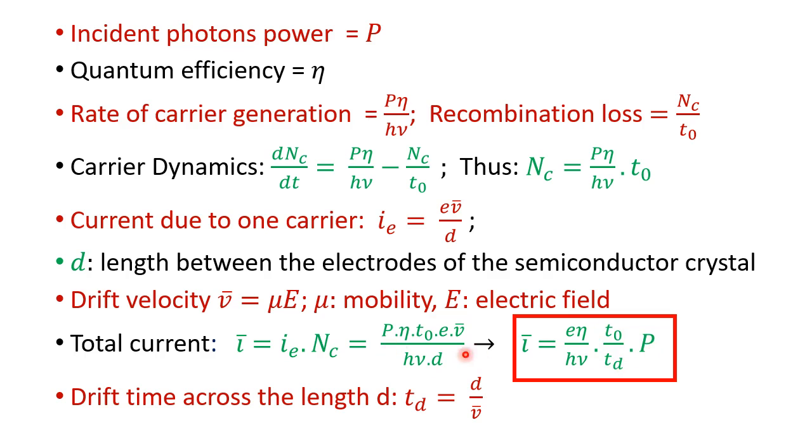This supports my statement which I had made earlier, that it's only this fraction that contributes to the current in the external circuit. So there is a drift time, a specific time required given the particular bias. There is going to be a certain drift velocity associated, and one is comparing that with the lifetime of the electron before it is lost due to recombination. That is an important relationship that we will come back to when we look at the shot noise.